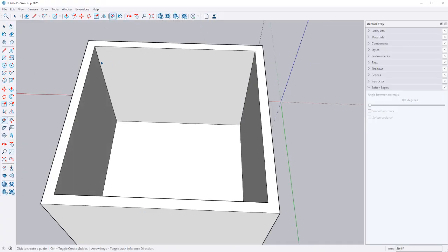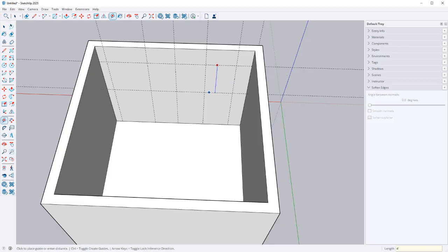So what I'll do is take this, reference here, and then our door is going to be 6 inches from the edge. It's going to be 2'8" across, and it's going to be set up at 6'8" for the height. And then let's say I've got a window over here. We can put the window at, let's say, 3 foot from that wall. It's going to go 2 feet out in each direction, so I'll offset this twice in each direction, and it's going to be a 4 foot tall window.